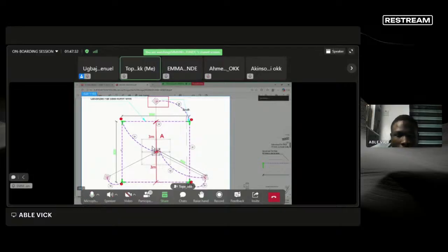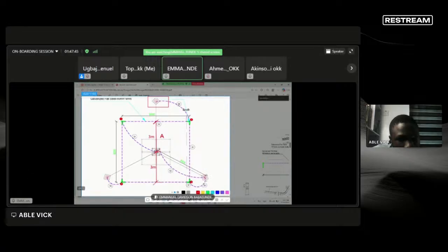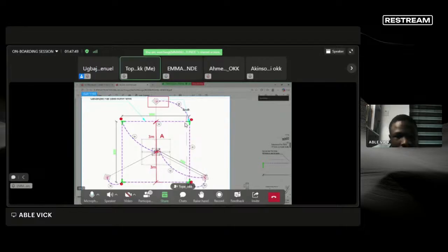At that earthing bar you will attach the flat bar to the base plate at 2 meter. That flat bar has to come up to the ground and connect to this ring.